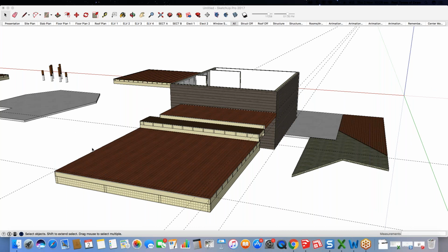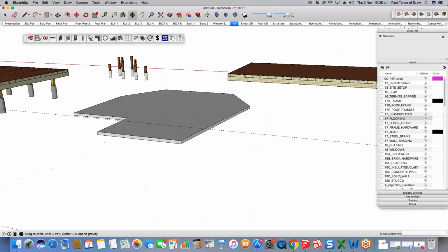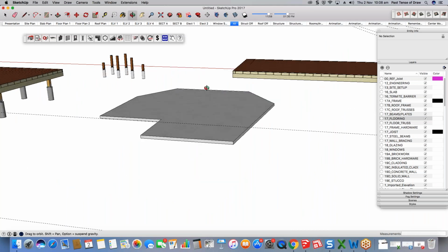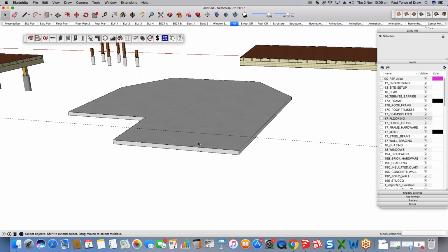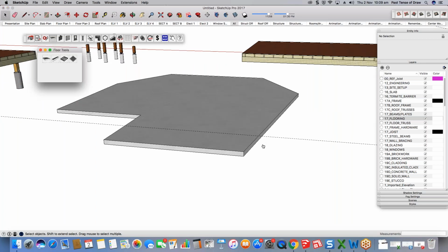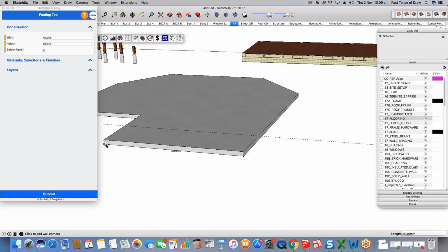Okay, sloped continuous concrete footings. So 100%, you can go into any level of detail that you want. Sometimes it can actually be really beneficial just to use the SketchUp tools and then dim them, and you're still going to have them quantified if you're doing something really bespoke. But say, for example, I went into my footing tool and I know that I want it to be sloped. I'm just going to show you this, because again, it's a manual override, but it's pretty powerful.